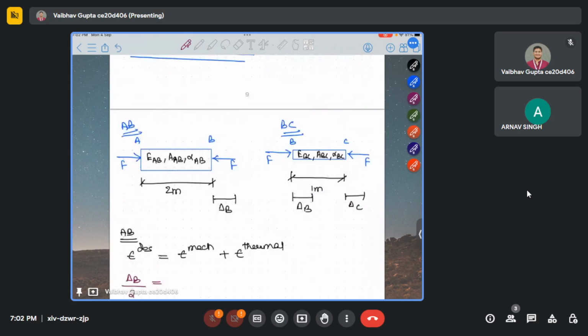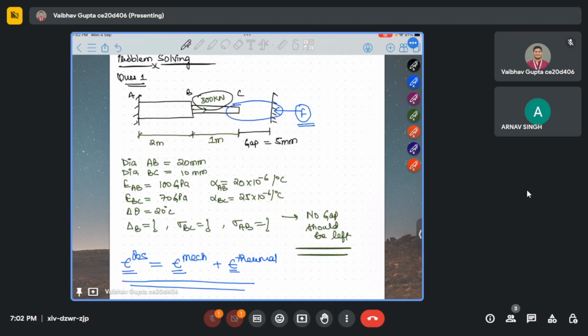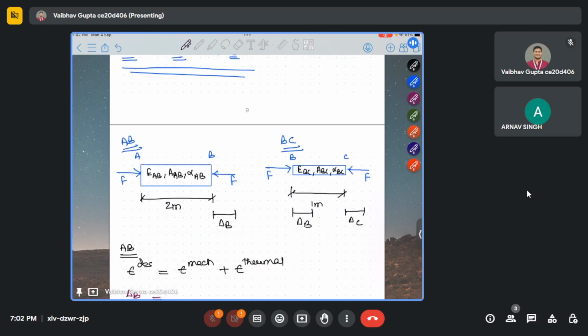Okay. I missed one thing; I didn't mention it. We applied the original force of 300 also here. So 300 is already acting at B point. So overall force acting towards positive X direction has a magnitude of 300 minus F. So here at A also we will get a reaction to maintain equilibrium, which is equivalent to 300 minus F. Okay.